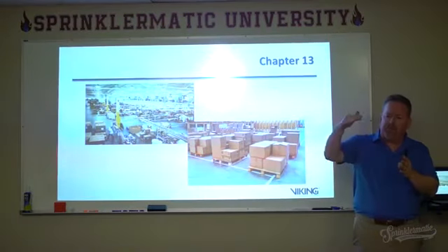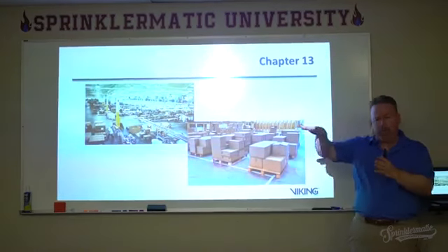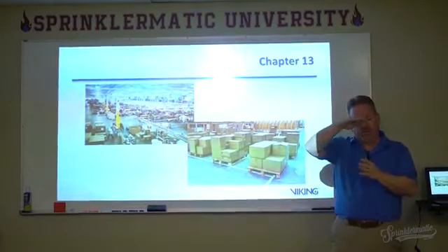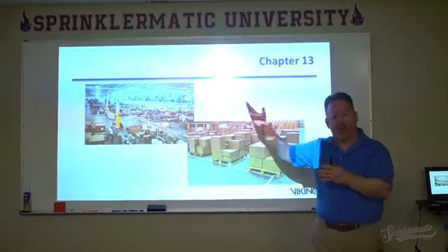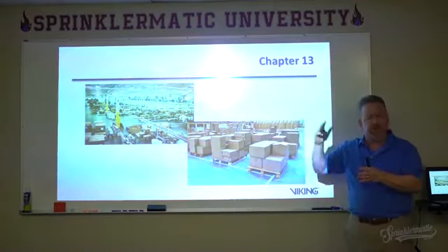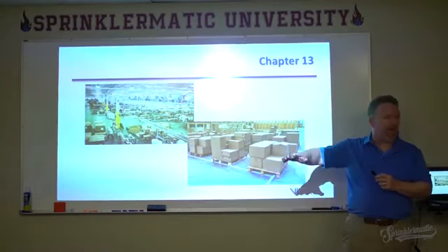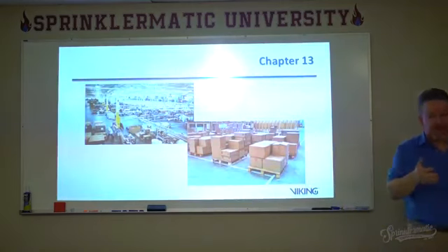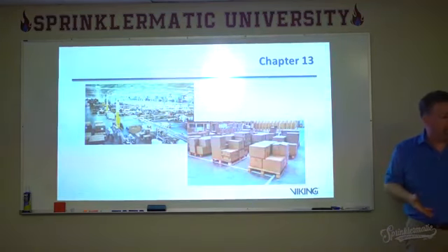They all stop in their storage height at 12 feet. Okay, so at 12 feet, that's kind of the end of occupancy class. If you have storage above that, you have to go to the storage occupancies. However, you do have certain warehouses that are storage. That's what they do, but they don't store above 12 feet.